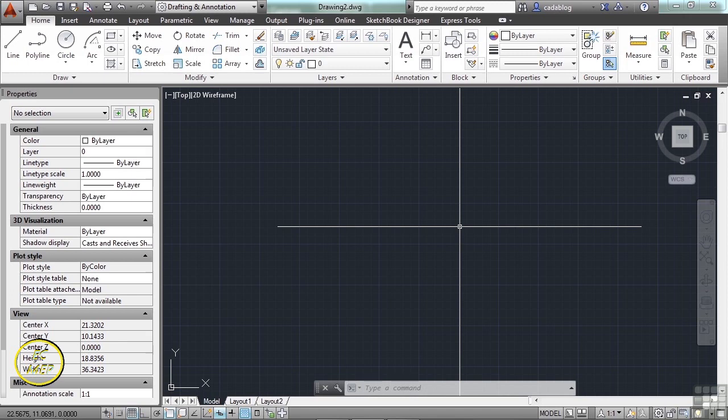You can then control the following: whether the objects on a layer are visible in any viewport in any instance. You can control whether and how objects are printed. You can control what color is assigned to the objects on the layer. You can control what default line types and line weights are assigned to all of the objects on that layer. You can also define or control objects on a layer and how they can be modified, or even if they can be modified. You can control whether objects are displayed with different layer properties in individual layout viewports.